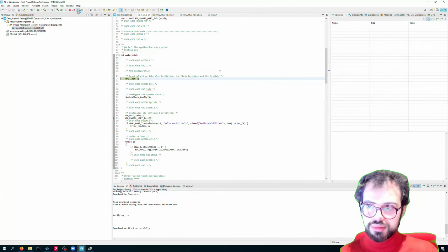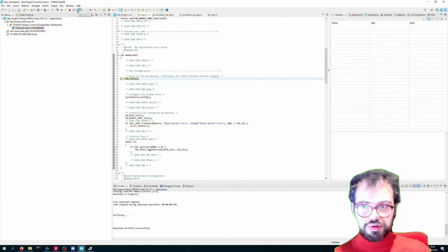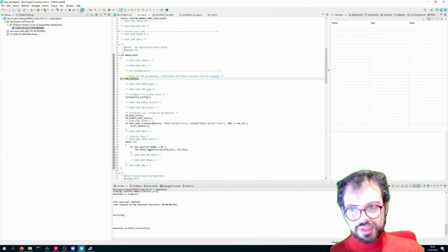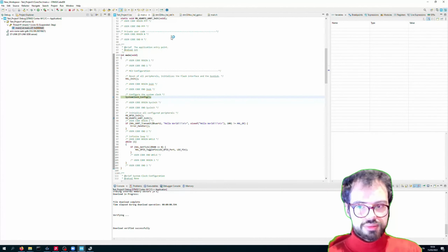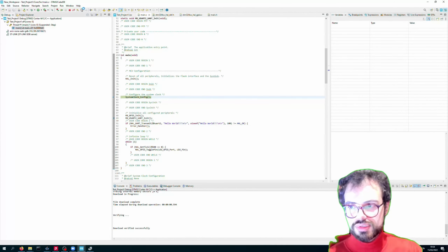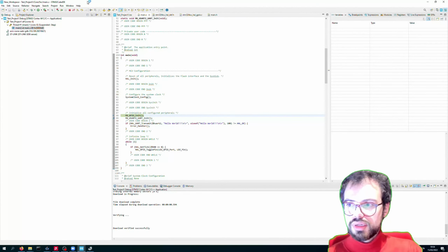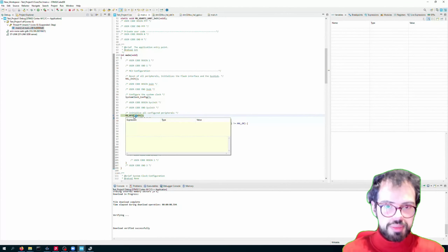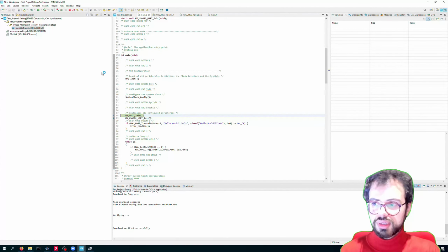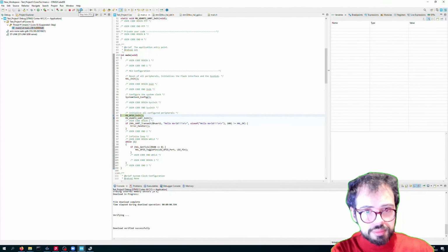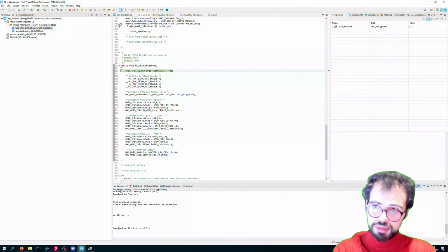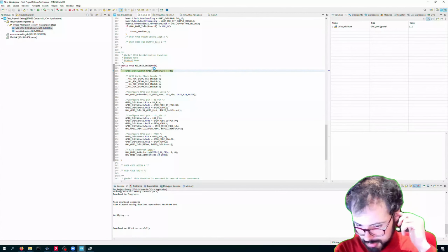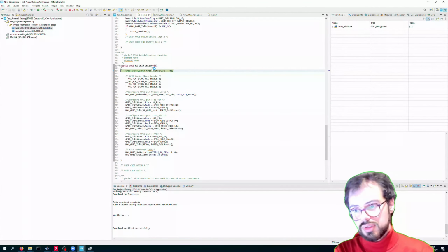Okay, here you can go. You have the option of going over the function. So if I go into step over, it will do the all init by itself. If I do it on the sysclock again, if I want to see what is going inside this function, because maybe there is a problem, a glitch, I can do step into, and it will go inside the function that it was overlaid and it was highlighted before.